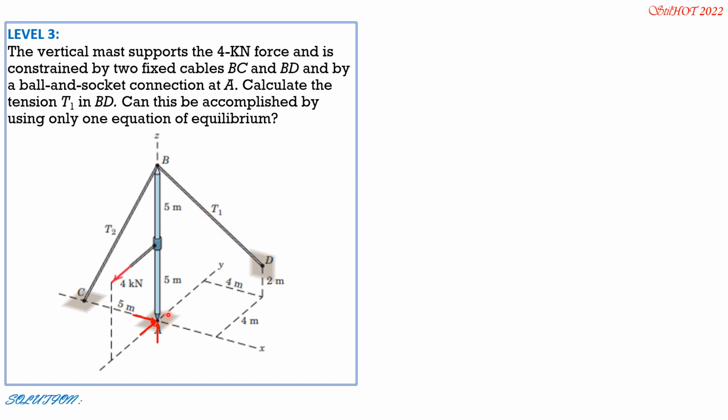So these are the component reactions at A. It's a ball and socket joint, so 3 forces. At C, horizontal along X and along Z components. But we will not name them because if we sum up moment about X, all these forces and reactions or components are not involved. Then T1 in vector form is going down 8 only, going down along Z. Along X, positive 4. And along Y, in that direction, is also positive 4.